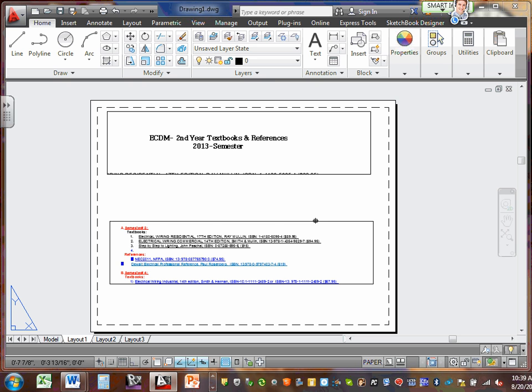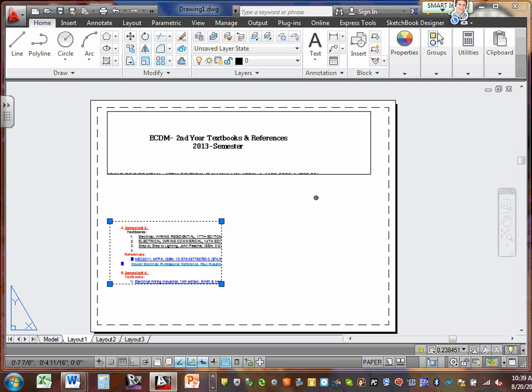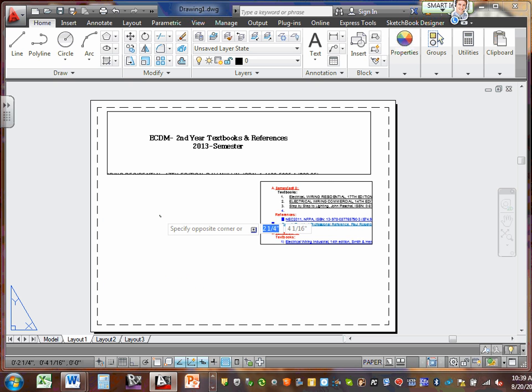Look at that. I can have a viewport that comes from here, sitting right up to here. Even shape-wise, I can click on it, hold it, drag it and put it right in here, adjusting it in the drawing. So when you print, it will print wherever you put the viewport.